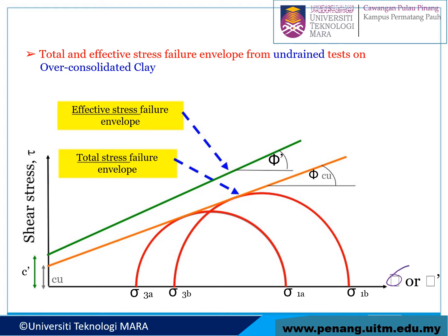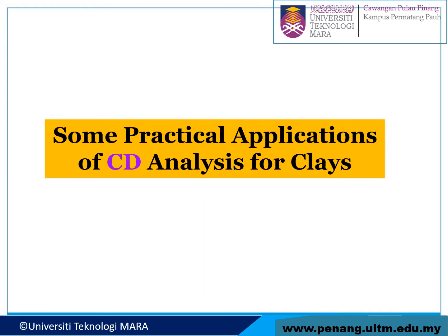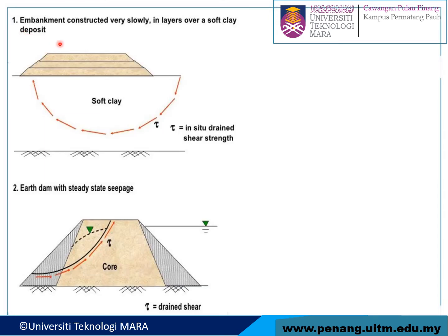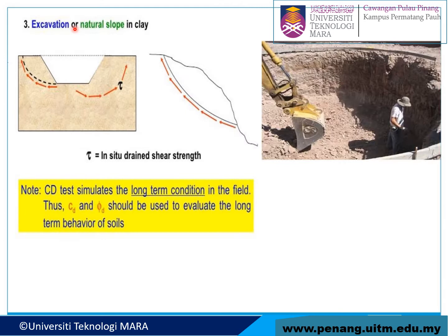Now we look at some practical applications of CD analysis for clay. First, an embankment constructed very slowly in layers over a soft clay deposit. Then, a dam with steady state seepage, and an excavation or natural slope in clay. CD tests simulate the long-term condition in the field. Those C and phi should be used to evaluate the long-term behavior of soil.